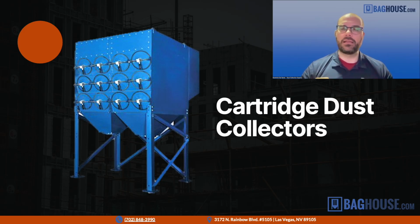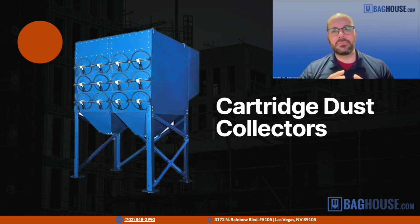In mining and cement, we don't see them used so much because most applications for mining and cement have a lot of dust that comes in. Cartridge collectors are especially good when we have a lot of air to clean that has a little bit of dust in it. In those applications, they absolutely make sense, and they can be a lot cheaper than a baghouse style. Now, there are some differing opinions. A few manufacturers recommend them for cement and mining applications. Most in the industry, however, decide not to use them.